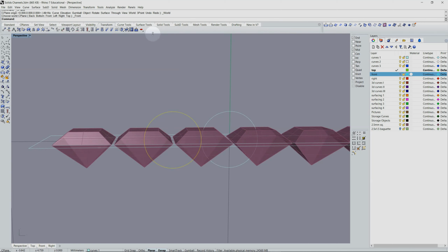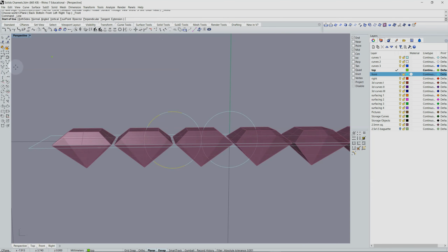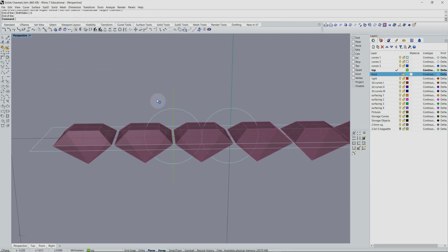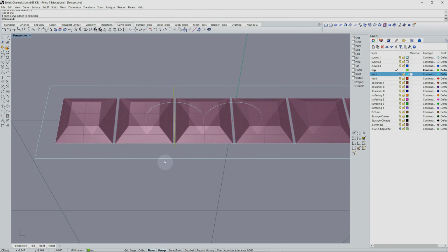So I will go to the Curves tab and then select the Single Line command from the side toolbar. The start of my line will be the center of the new circle, so activating Center Snap, I will touch the edge of the circle and select the Both Sides option from the command line. Then I will hold down the Shift key and pull this curve straight vertical up and down until it extends beyond the circle. I want to create 2 additional construction lines to establish the width of the bar.